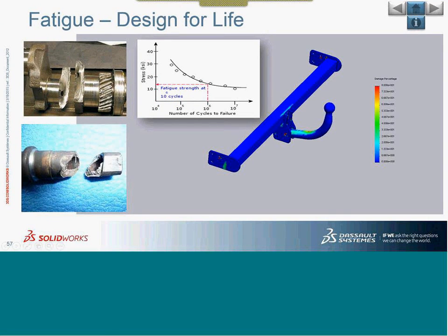For shafts, it appears as though they are rotating in a circular way, but in fact, at a given location, the shaft will be undergoing everything from a tensile load to a compressive load. Of course, it depends on the loading conditions, but it really can happen. Or the example shown in the video, where it could also be a torsional thing.